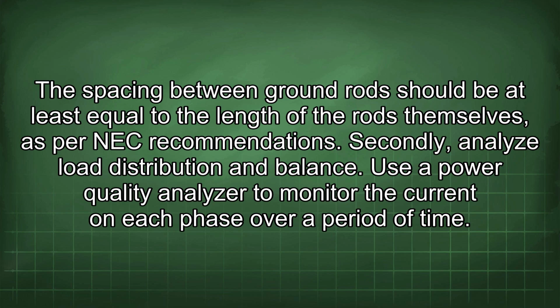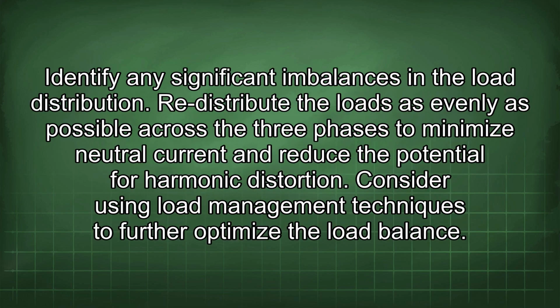Use a power quality analyzer to monitor the current on each phase over a period of time. Identify any significant imbalances in the load distribution. Redistribute the loads as evenly as possible across the 3 phases to minimize neutral current and reduce the potential for harmonic distortion. Consider using load management techniques to further optimize the load balance.